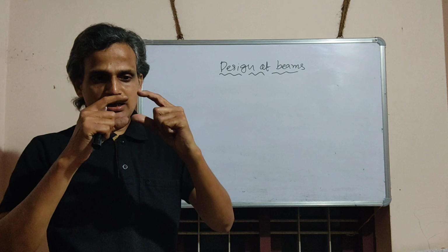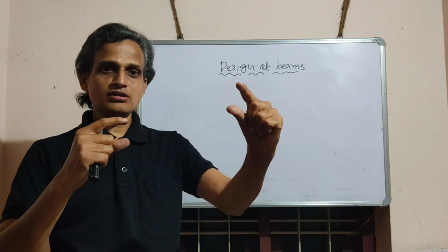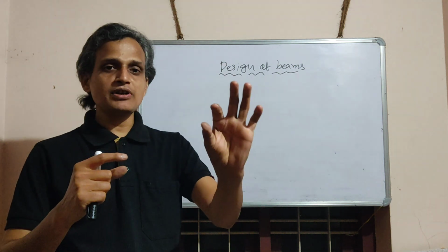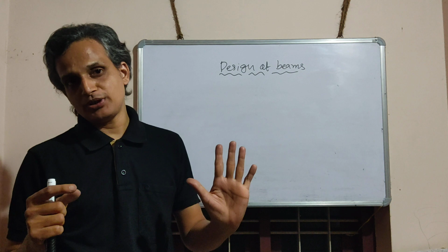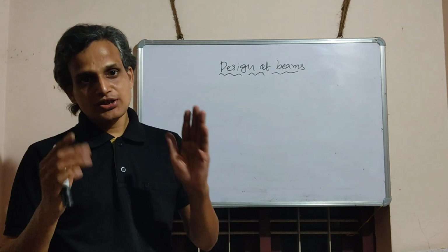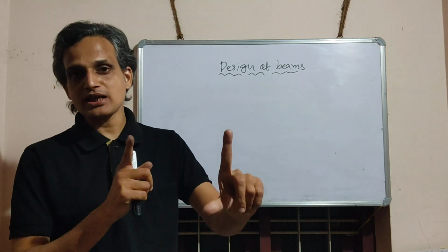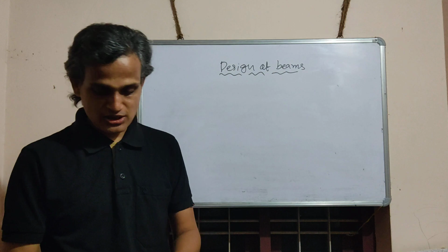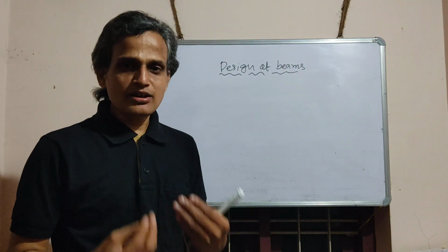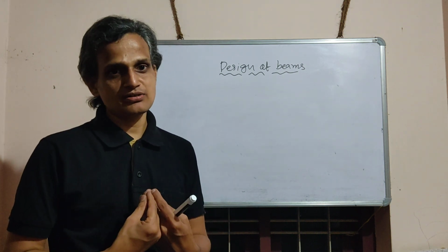Remember, anytime you are writing shear, there will be a root 3 in the denominator. Shear is always with root 3 and fy is always accompanied by gamma m0. This is one important factor because we can expect some questions like this.